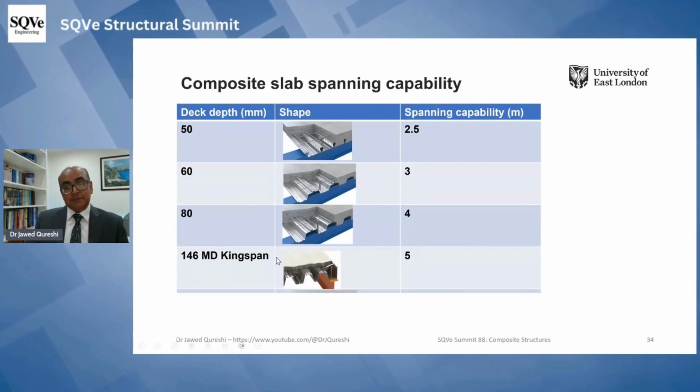And if you work out the strength of the shear stud connection using this decking, using the Eurocode formula, you will get wrong results. That will not be realistic. So this is a knowledge gap that needs to be filled.